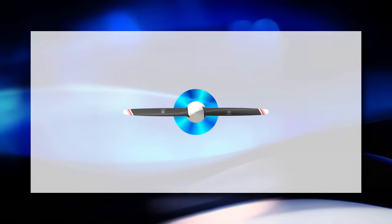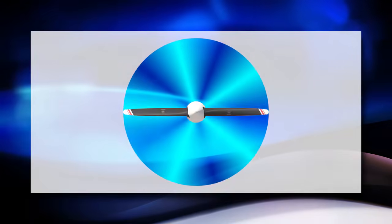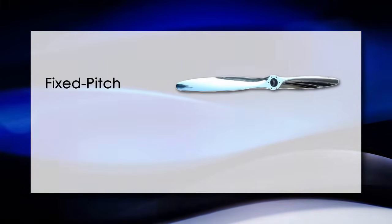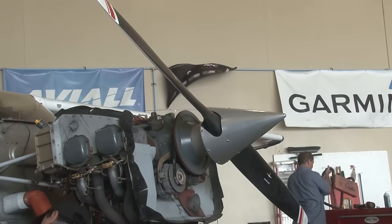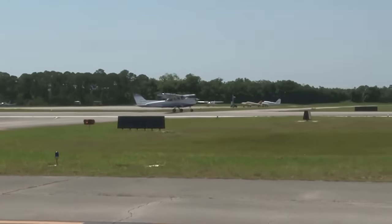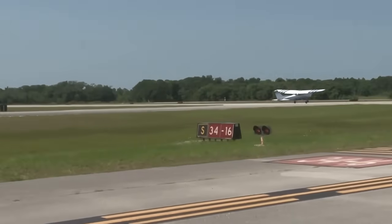Since the propeller rotates around its hub or center, the further the propeller extends out of that hub, the faster it spins. To create equal force throughout, manufacturers twist the blade. There are two major types of propellers: fixed-pitch propellers and constant-speed propellers. The Cessna 172 is equipped with a fixed-pitch propeller. This means that the pilot cannot manipulate the propeller blade. It is installed onto the airplane and will always remain exactly how it was installed.